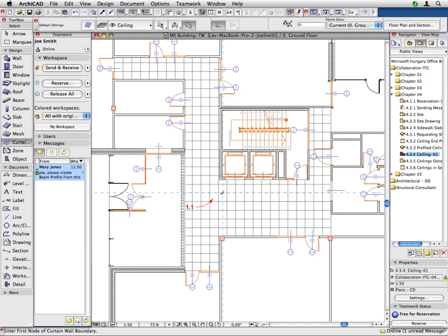The applied curtain wall favorite refers to a 60 cm by 60 cm suspended ceiling grid. As you can see, ArchiCAD's curtain wall tool can be perfectly applied to represent not only curtain walls, but also suspended ceilings, which also consist of a grid-like structure.